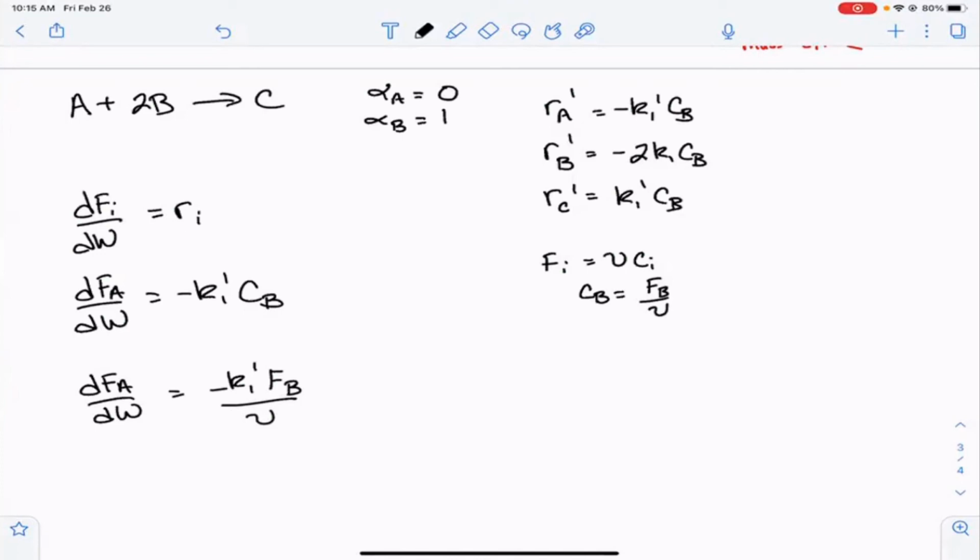To do that, we're going to start with the flow version of the ideal gas law. We're going to say that PV over P0 V0 equals FRT over F0 R T0. And we were told in this problem that the pressure is constant. It's isobaric. And that'll be something to talk about later on as well. We're going to do a lot of problems here where we assume the pressure is constant. And in a plug flow reactor, that's fine. In a CSTR, that's pretty good.